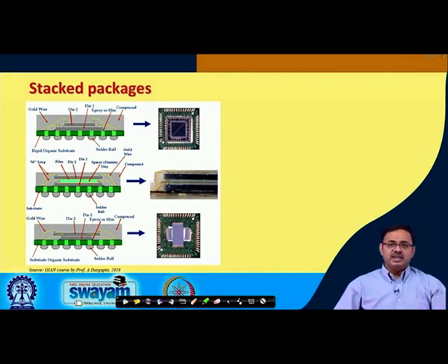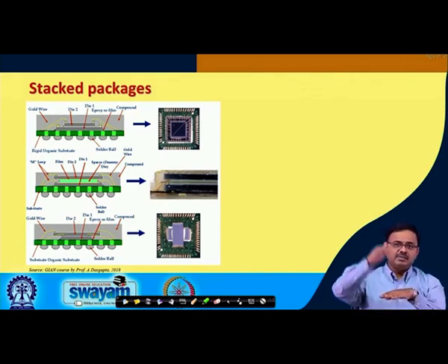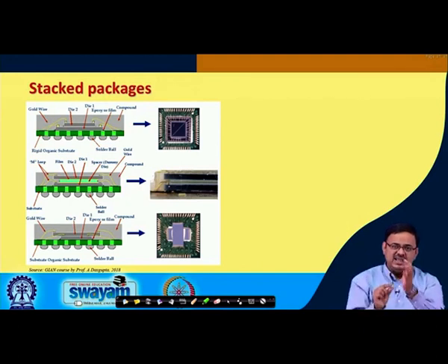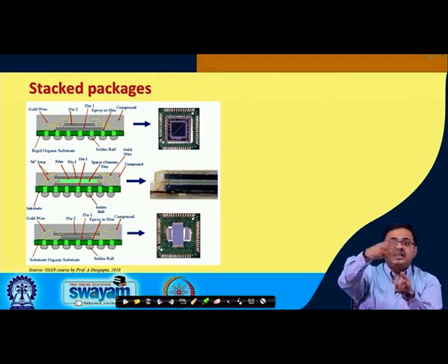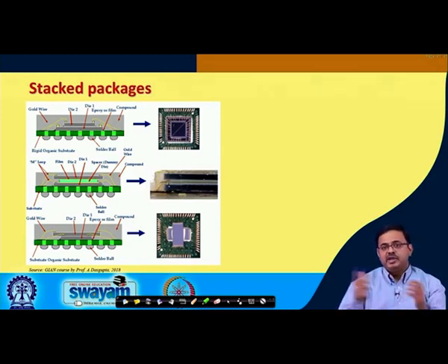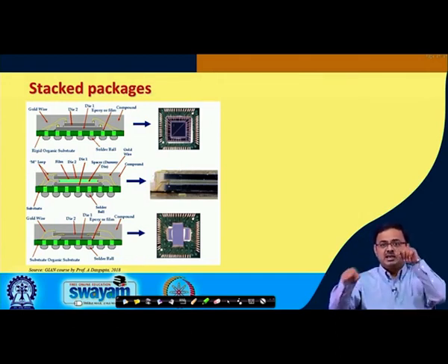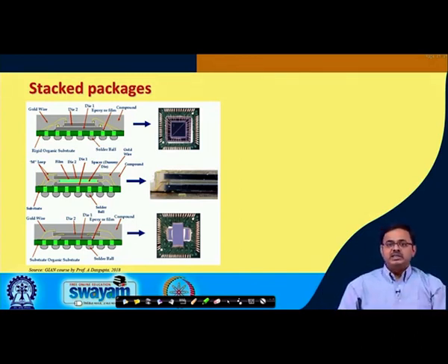The thermal engineer will say that is the worst design. You are lining up the hot spots, I will just have a single area along the 3D stacking where entire heat will be generated. It will be a nightmare for me to dissipate the heat, and in no time will your temperatures just shoot up. If you want a good thermal design, and you have two dies, place these hot spots farthest away from each other. Now, that would be a very good thermal design, but not the best electrical design, rather probably among the worst electrical designs. So, how do you come to a compromise?